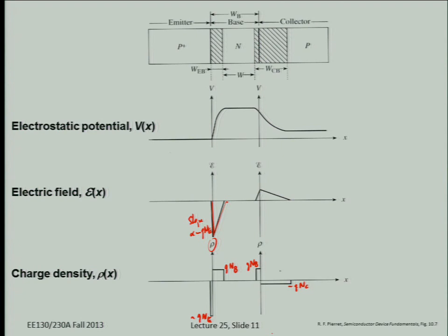Okay, and as I mentioned, there's a difference here due to the difference in doping concentration between the collector and the emitter. So if the collector is doped 100 times less heavily than the emitter, what would this difference be? It's 120 millivolts, right? If there's 2 orders of magnitude difference, it's 60 millivolts per decade of change in doping, for N E over N C equal to 100.